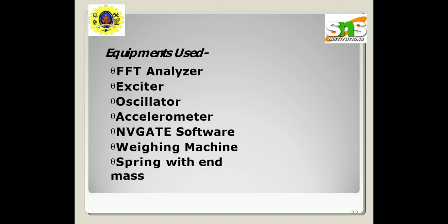The natural frequency of the tuned mass damper is basically defined by its spring constant and the damper ratio determined by the dashpot. The tuned parameter of the tuned mass damper enables the auxiliary mass to oscillate with a phase shift with respect to the motion of the structure. In a typical configuration, an auxiliary mass hung below the nacelle of a wind turbine is supported by dampers or friction plates. So, dampers in buildings and related structures use huge concrete blocks or steel bodies mounted in skyscrapers or other structures.